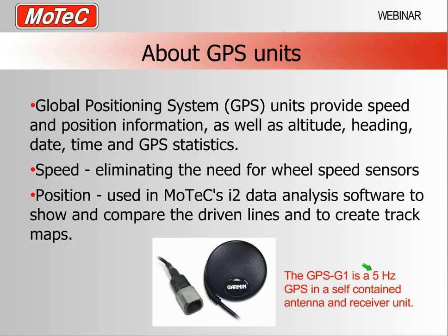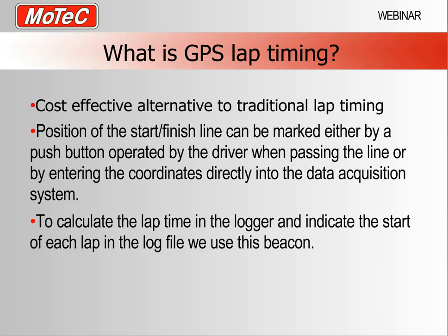The positional information from a GPS can be used within MoTec's i2 data analysis software to show your driven lines and to compare them and also create your track maps. So you can get quite a lot out of a GPS unit.